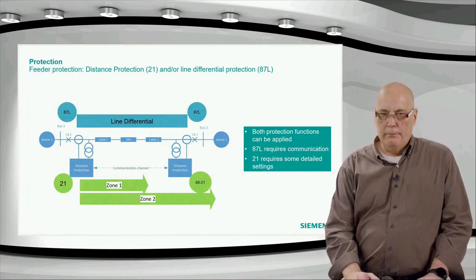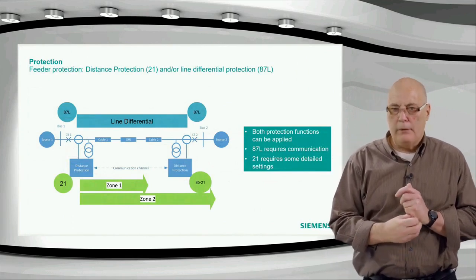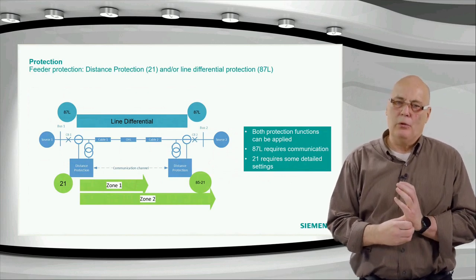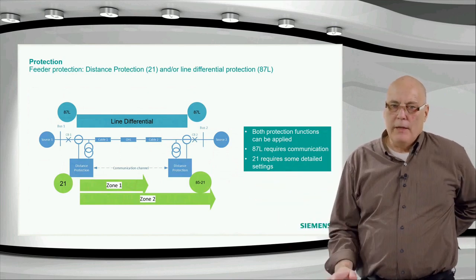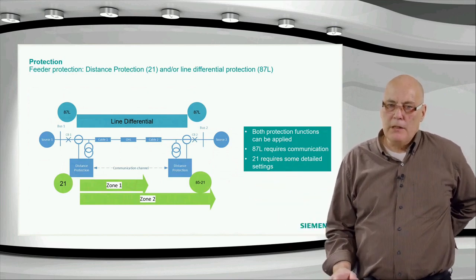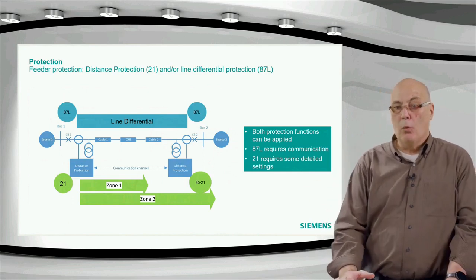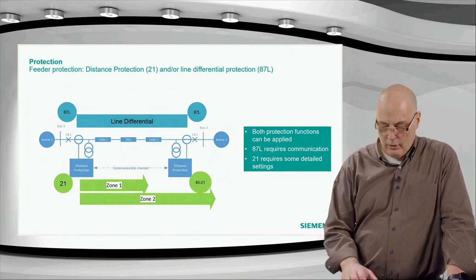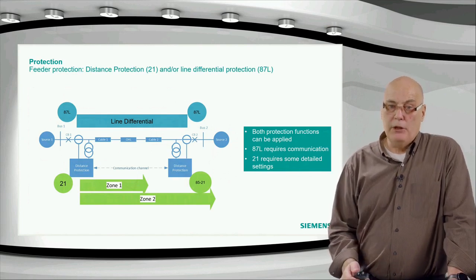All right. That is interesting for normal application, but I said there are obviously special conditions, and we want to look a little bit at some special conditions. And one special condition is the mixed feeder. There are different reasons for mixed feeders. We have been getting more and more of them these days as people go underground near rural areas and so on. But whatever the reason is, the distance protection must cope with that.